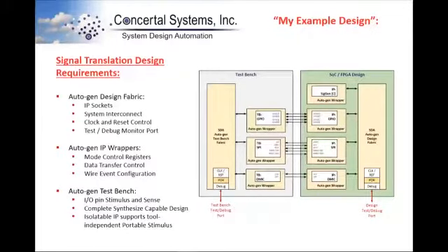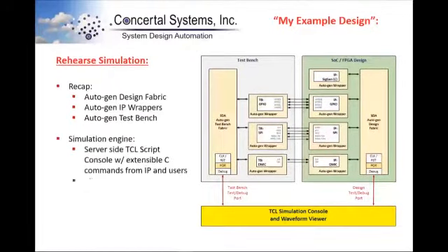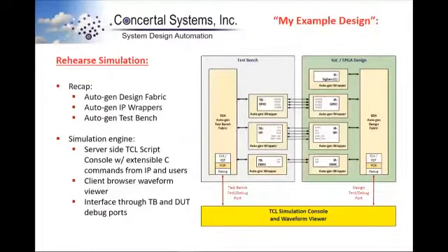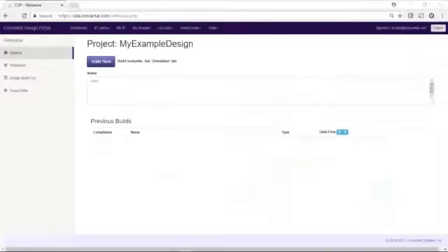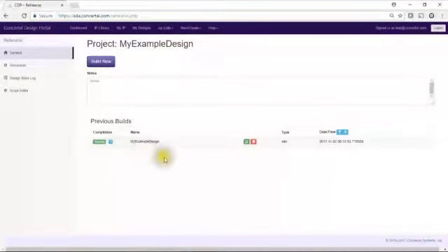It's building another design which acts as a test bench to the main design, allowing us to apply stimulus to all the input pins, as well as to monitor what's going on with the output pins. It's building the debug ports to the simulation environment and compiling all this together as a simulation with a Tcl-based user interface. As you can see, the build is now complete, and we'll refresh the screen. And as you can see, we now have a compiled design ready for simulation and Rehearse.